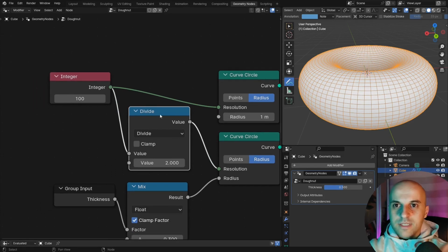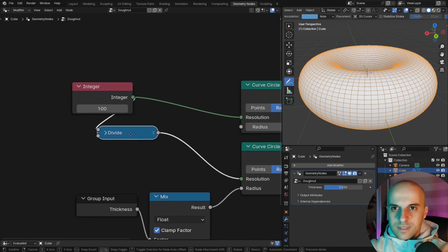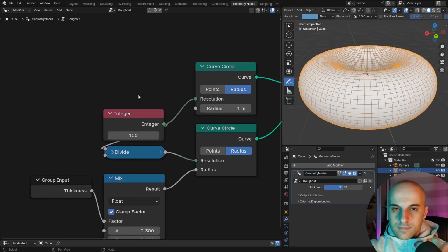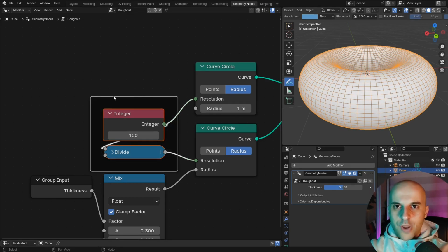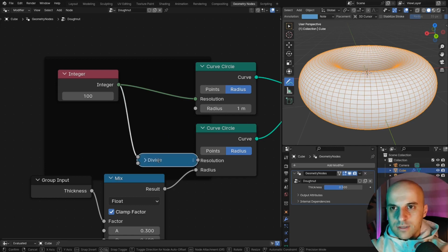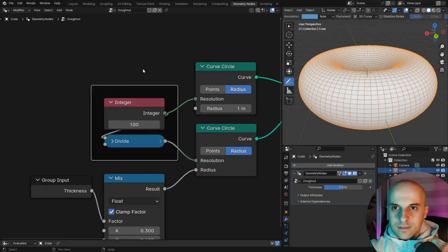This math node is a bit big now, so what we can do, if I press H, it will collapse it to this neat little thing that I'll place underneath this one. Furthermore, if I select these two and press Ctrl J, it will frame this in this frame node. Now I can move this as one whole thing, and if I move this individually, the frame will update around them. Then with this selected, I can press F2 to rename it, so I'll call this resolution.